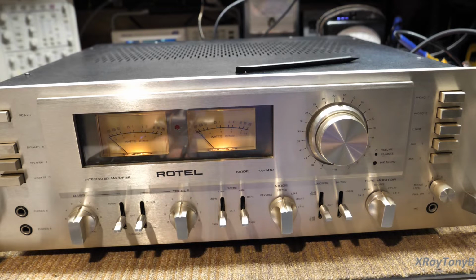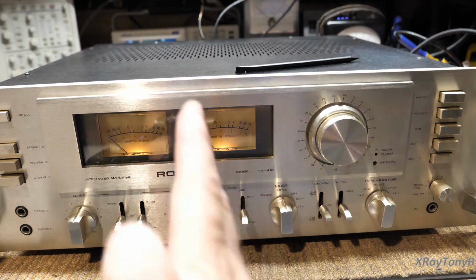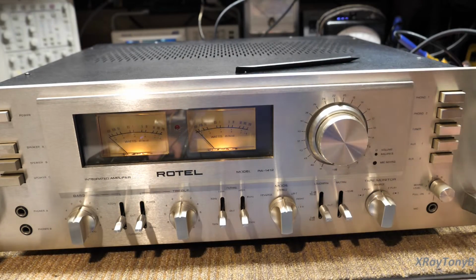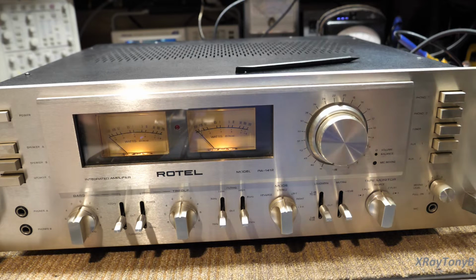But what it will not show you is how it changes the phase of the input versus output signal dependent upon frequency. So we saw that it didn't change the amplitude, but it did in fact change the phase at low frequencies and at high frequencies. And in the middle range of our hearing range, it was unity. It didn't change the phase whatsoever. So the frequency analysis does give you that one extra function that you can check.